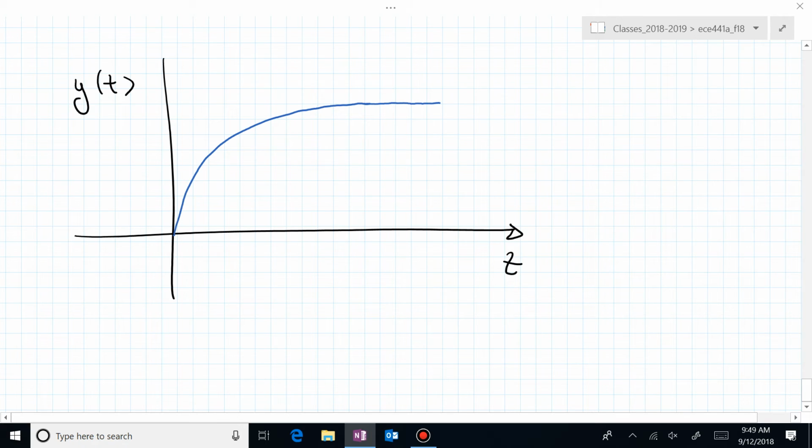That's a first order system response. There's no wiggle about it. It just exponentially goes to its final value. What we want to do is now say, you have a black box. I'm going to apply a constant input to that black box, and then I'm going to tell you what's inside that black box in terms of its transfer function. That's what we're doing with system identification.